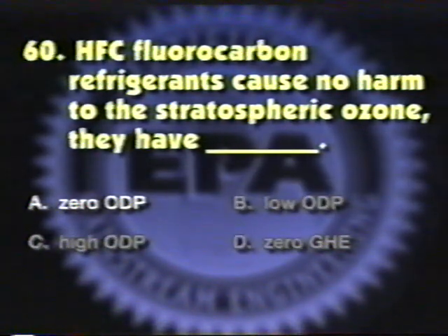The answer is A. HFC refrigerants have a zero ODP and cause no harm to stratospheric ozone. They do, however, contribute to global warming, just like HCFCs and CFCs, and cannot be vented.